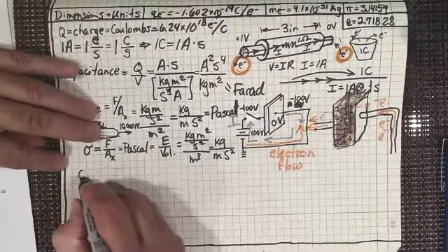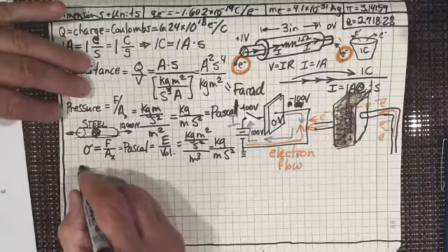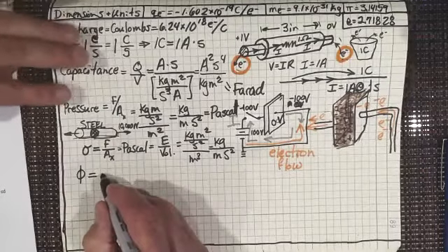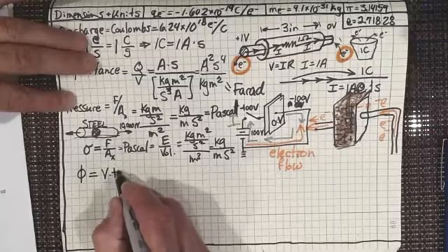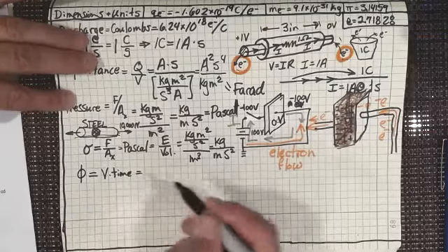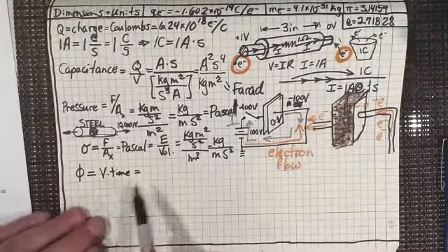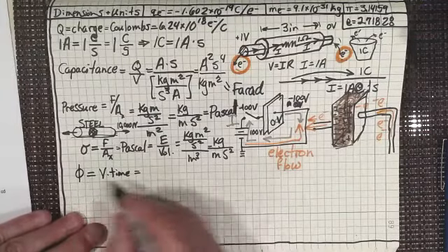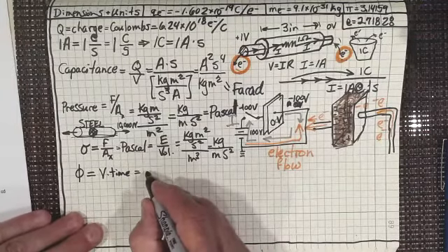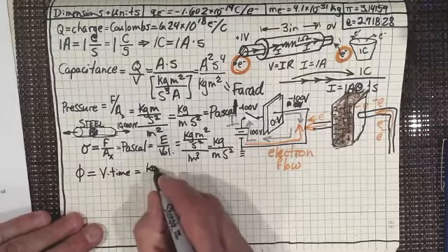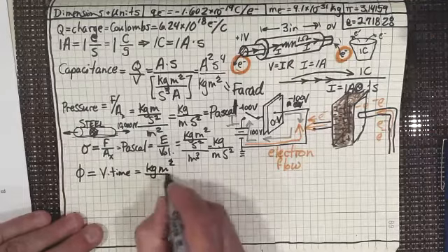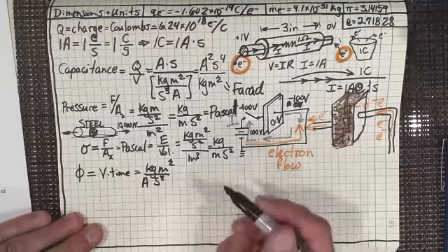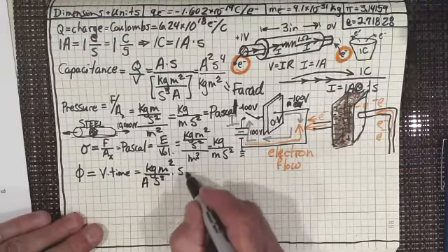So magnetic flux, right? Magnetic flux is, well, let's say voltage times time. I just want to get this out. And we'll have a much longer discussion of what magnetic flux is later, but just to talk about the dimension and the units of magnetic flux, well, we've got voltage, which is kilogram meters squared per seconds cubed amps, times time, which is just a second.